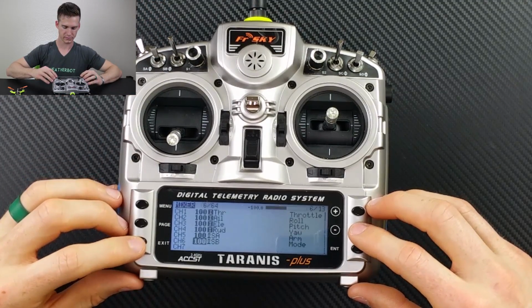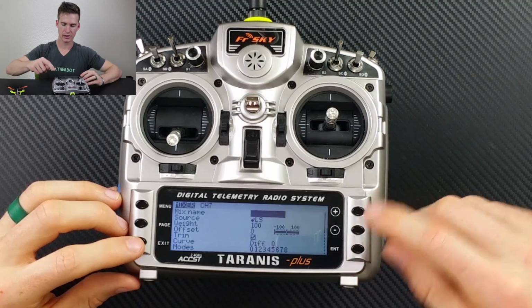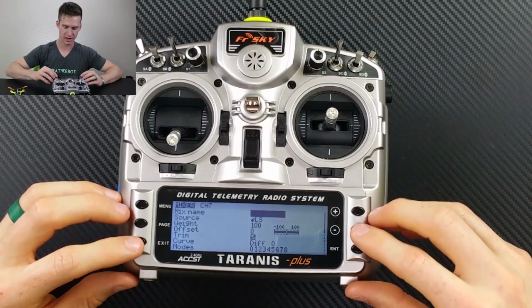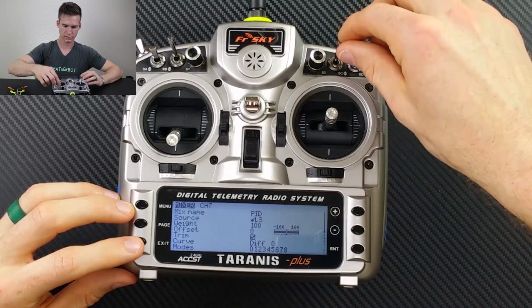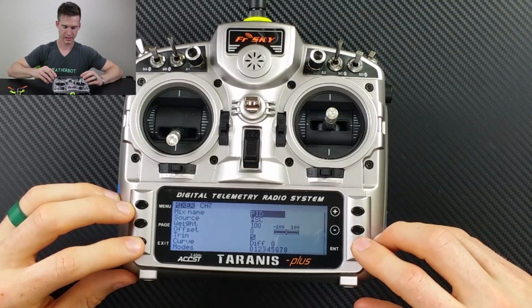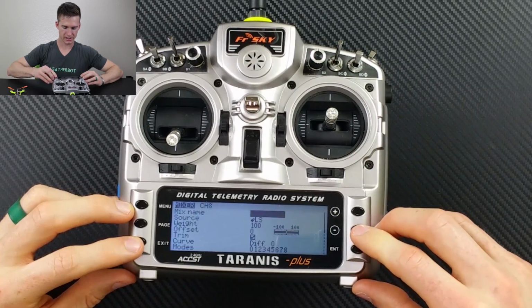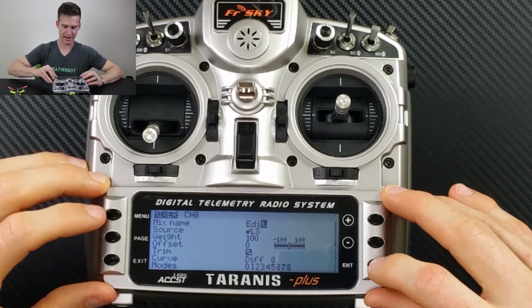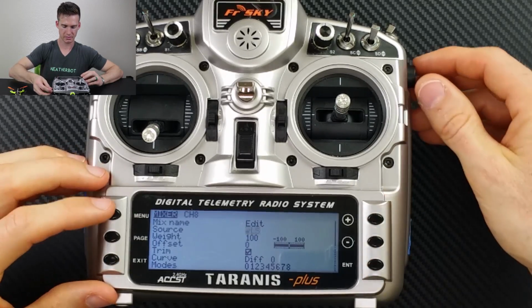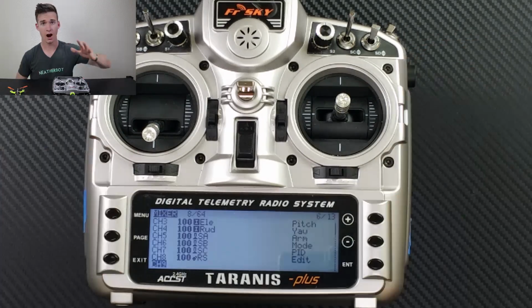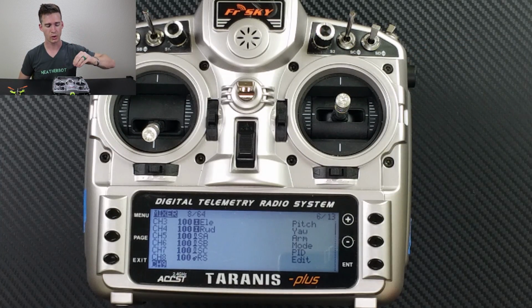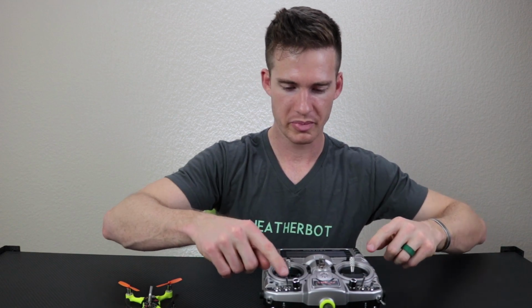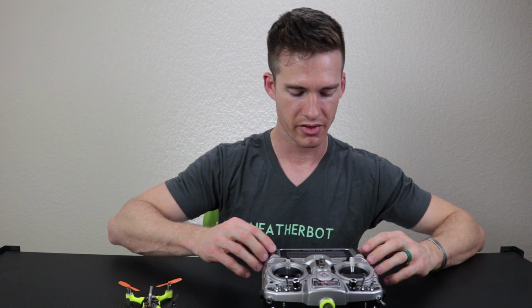We'll come out. Our third auxiliary channel is going to be our PID selection. So we're going to be able to select between P, I, and D with this switch. And I'll explain that when we get to Betaflight. And then our last auxiliary channel is going to be the one we use to edit the values. So I'm just going to call this one edit. And that's going to be this RS on the side. All right, so now we've got all of our switches set up with the corresponding correct auxiliary channel. We've got arm, mode, the PID selection, and then the edit switch. Those are all set up properly.